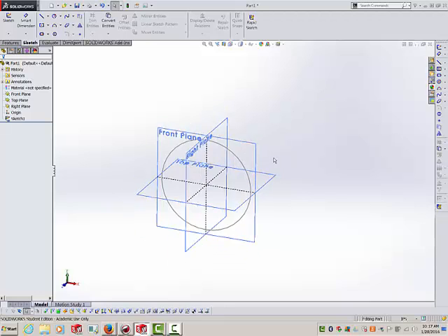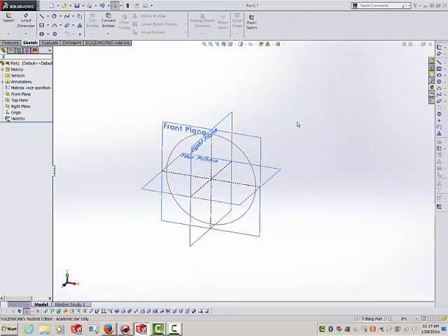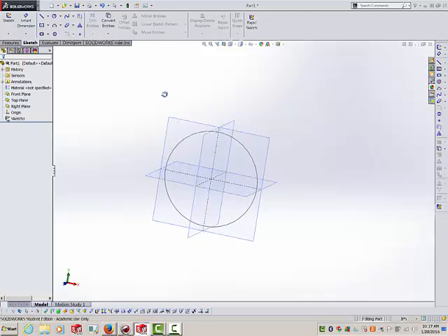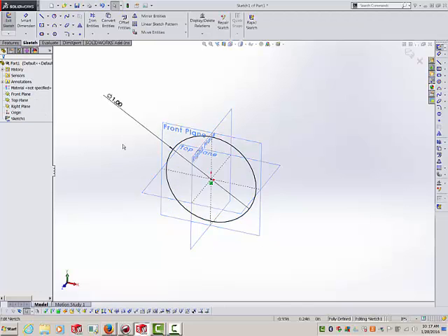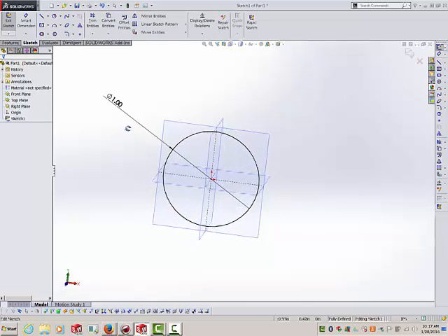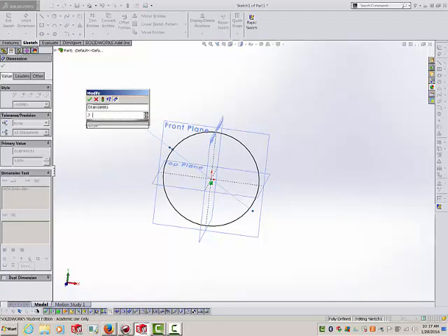So we are in what's called a 3D mode. And let's go in the sketch mode and back out again, just so you can see how I'm going from sketching to 3D back into sketching. So I'm literally in a 3D mode. There's no sketches that are active. But let's say I want to go into this sketch. I can go into my first sketch, and the context menu goes up, and I can edit sketch and get back into it. I could then change the dimension, 0.75 inches, say.